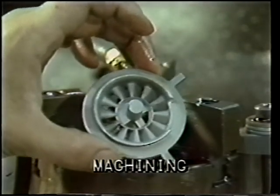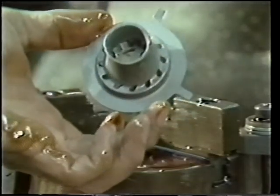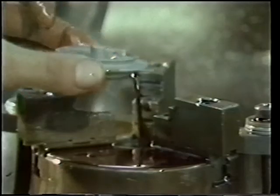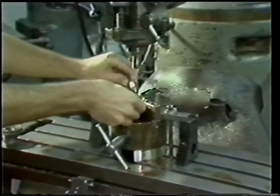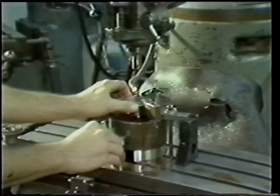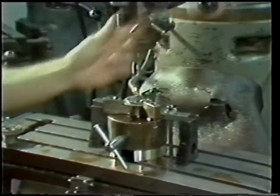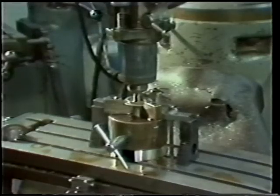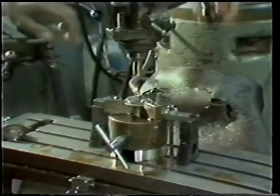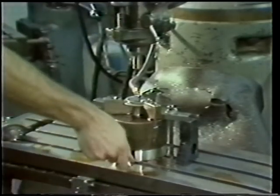Any remaining gates are machined off using a secondary operation. With combustor swirlers, the molten metal enters the mold cavity through channels in the center of the swirler. These gates are removed on a drill press using a hole saw, which can cut excess metal out of the round interior of a casting. Other methods, such as grinding and belt sanding, can also be used on certain parts when the gating is more accessible to machining processes.